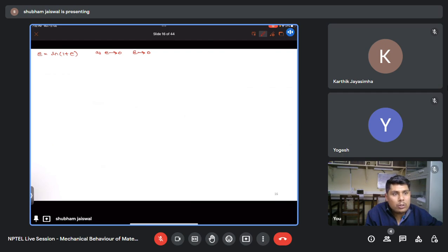Yes, in true strain we can add and subtract and we will get the same results. Whereas in engineering strain, if we add and subtract, we will get a different result. So that's why the true strain is known as additive in nature. Now after that, we have seen the normal strain on a 3D object.